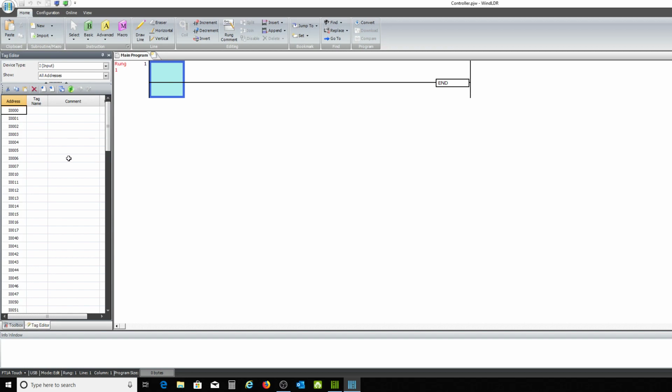Anytime I write a PLC program, unless it's something really small or something I'm just tinkering with, I'll go through the flow or sequence of work of the machine from start to finish, where the part enters, the part comes off the roll, where the water enters the system, and I'll start from there and sequence out my sensors, my inputs, and my outputs to my pumps, motors, turbines, or whatever it might be. And I list all of that stuff right here. That way I already have it in.